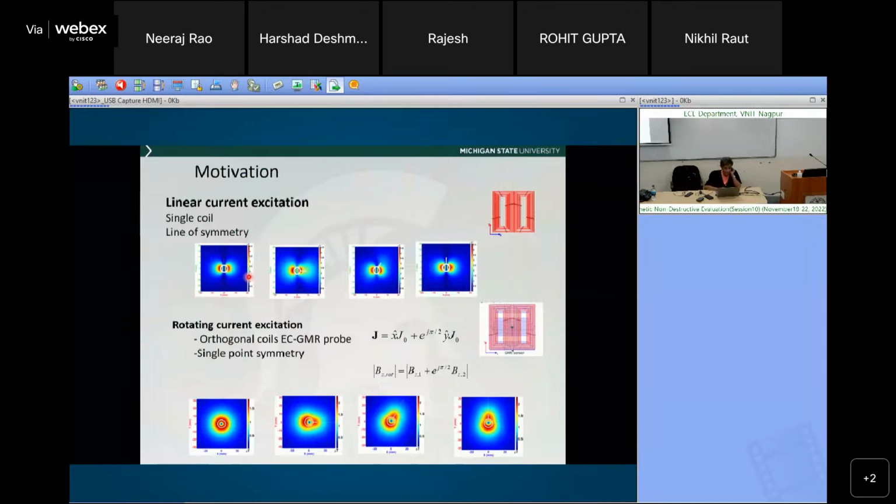And again, I think this is a steel, one is aluminum. With aluminum, you can get much more sensitivity, because the rivet signal, when I say aluminum, I'm talking about the rivet itself, or the fastener. When you have a steel fastener, then you have a strong rivet signal, but you lose the defect sensitivity and all that.